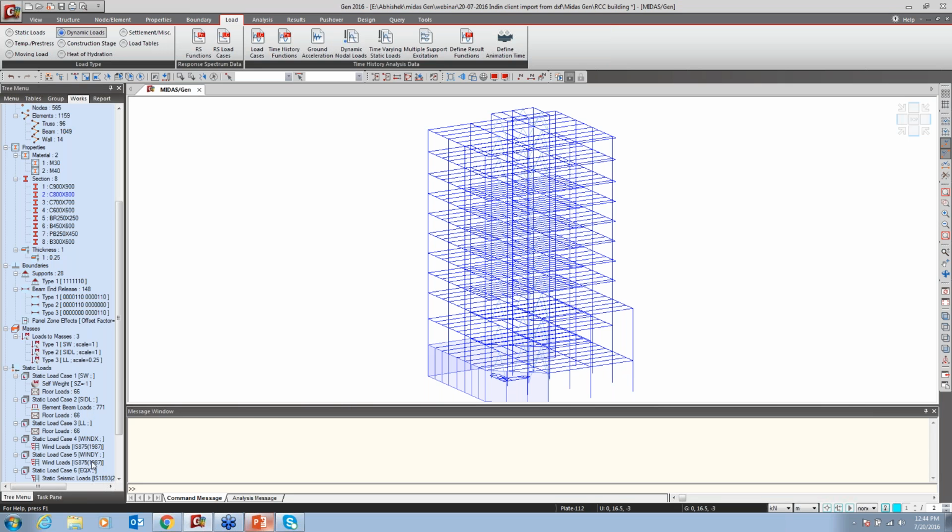Now one more question has come: how can we know the additional shears and moments? Actually, after that you have to check the center of mass and the center of rigidity, how much the difference comes. If it is more than that, then you have to take that one. And also see the normal moment, how much the normal moments are and how much my total moment is, means the design moment. See the difference. According to the difference you can see whether additional moments will come or not.